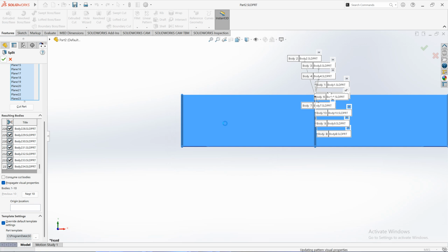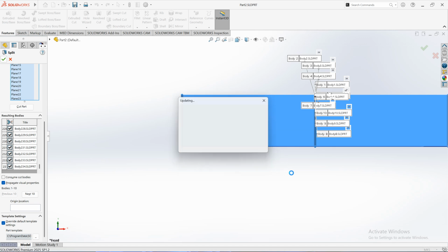Now, if you have a very uneven tank, where the diameter changes quite a lot from point to point, you can also do this using SolidWorks, but you need more skills. You need to be skillful in drawing the 2D sketch of the tank, or in some cases you need to draw the full tank and then work on it in its 3D model. You need to edit some parts in 3D models if you want very accurate capacity tables. But usually this is not required because you usually are not looking at this very high accuracy.